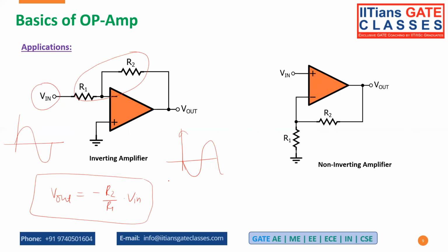The basic aim is to amplify the strength. The first element that we have used is the Wheatstone bridge, which will convert to some suitable voltage or current quantity. And then if its strength is not good, we have to use the op-amp circuit to enhance its strength. Similarly, we have the non-inverting amplifier. Its output is going to be 1 plus R2 upon R1 into V input.